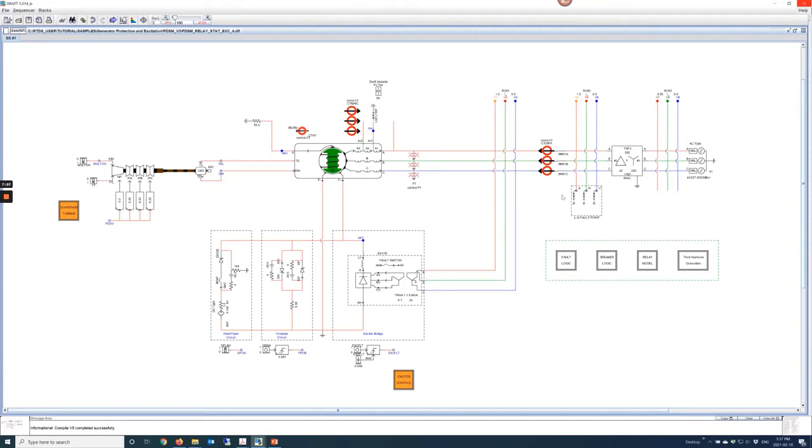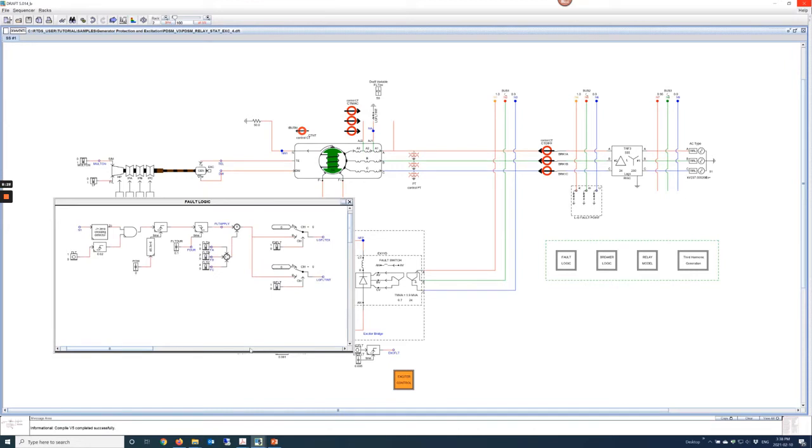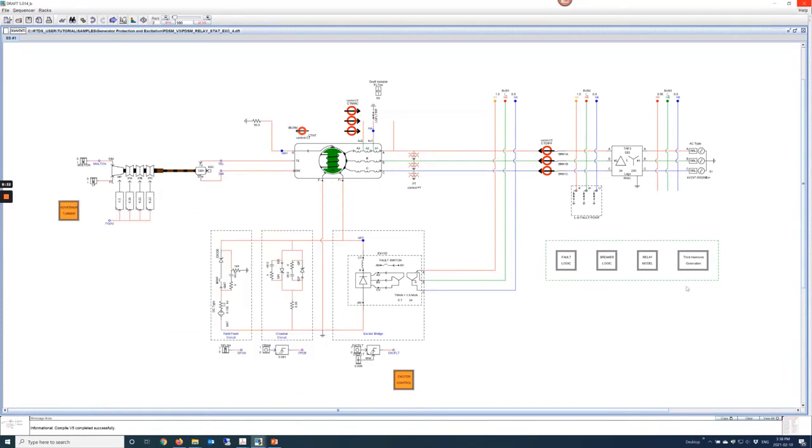Other components that you see in this circuit are fault components for external fault and internal fault between a stator to ground, or if you want turn to turn or phase to phase fault. CT to measure breaker current, CT to measure machine current and neutral current, and PT to measure machine terminal voltage. Also, you have fault logic, and using this fault logic, you can decide the type of fault, point of wave, duration of the fault, and location of the fault.